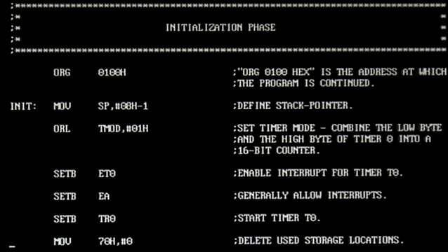With this program jump to address 100 hexadecimal, which I arbitrarily determined, the program generously skipped the entire range of possible interrupt entry addresses.